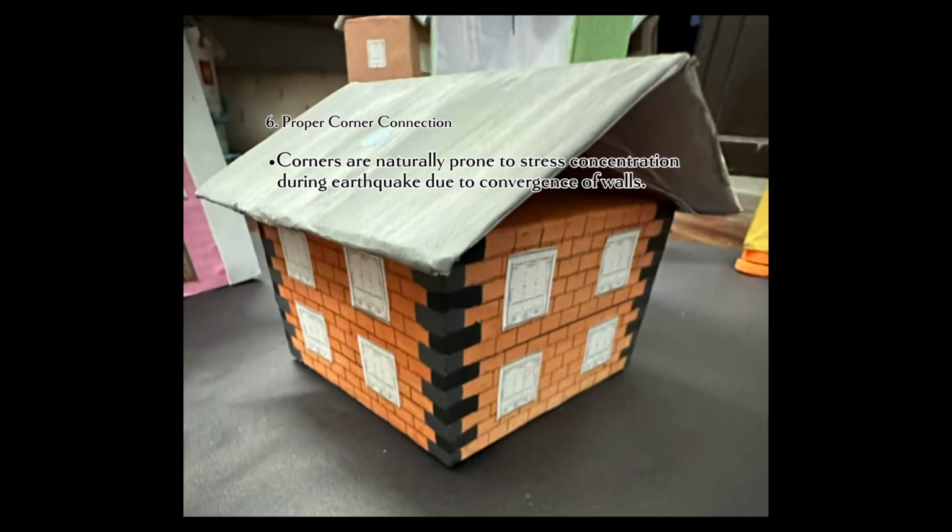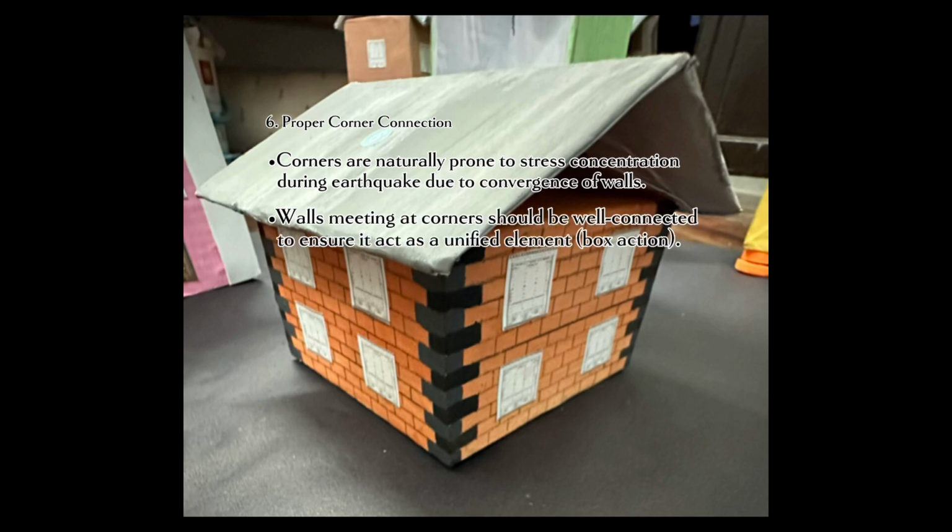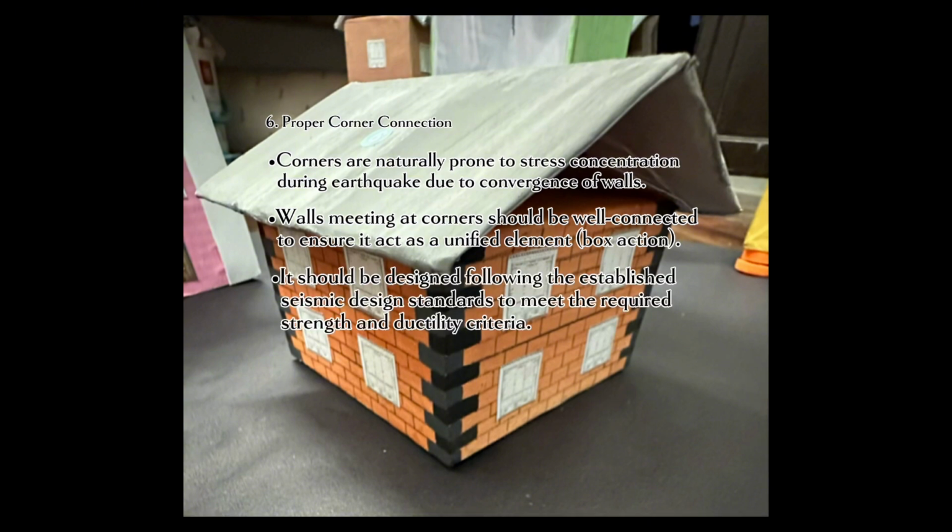6. Proper corner connection. Corners are naturally prone to stress concentration during earthquake due to convergence of walls. Walls meeting at corners should be well connected to ensure they act as a unified element, box action. It should be designed following the established seismic design standards to meet the required strength and ductility criteria.